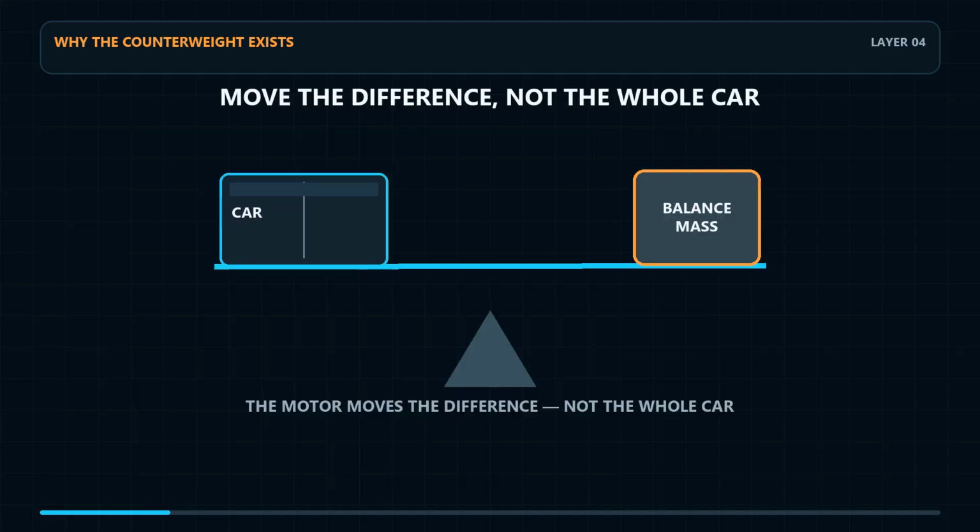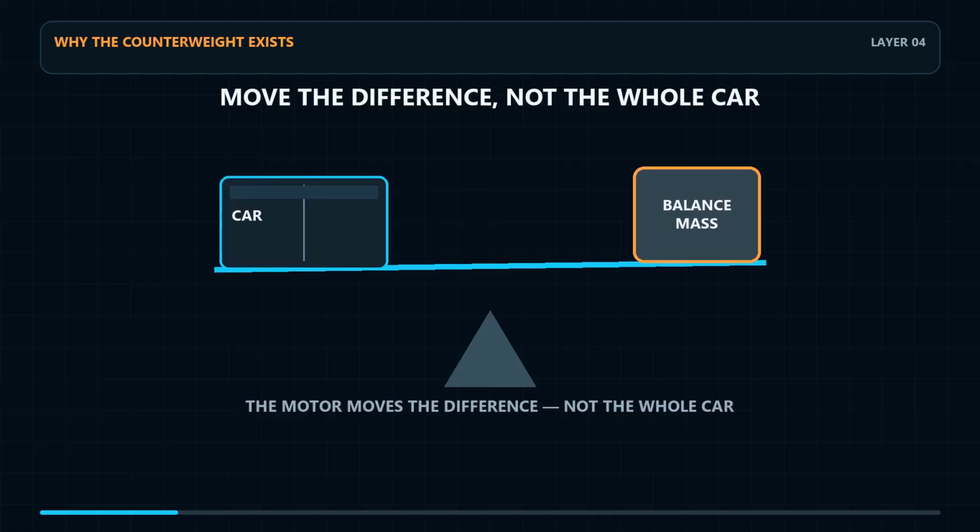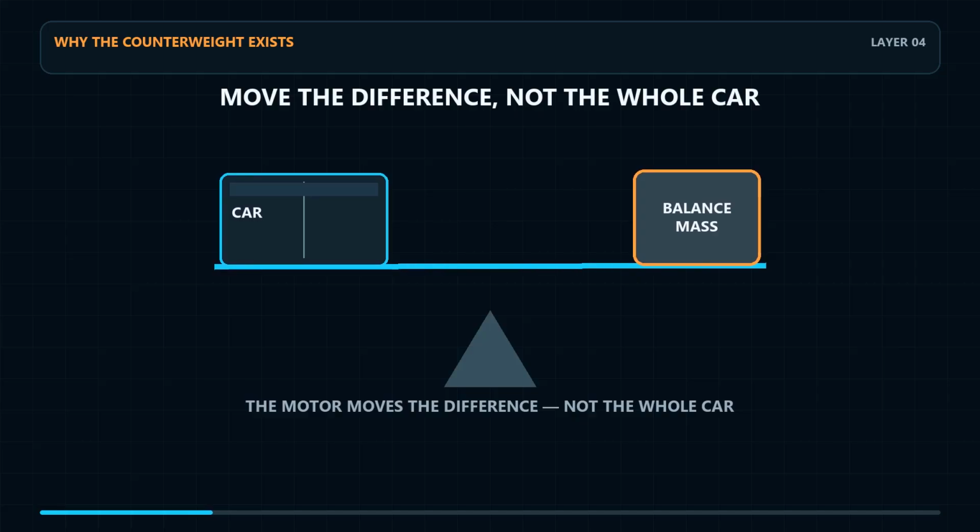The counterweight does not exactly match every passenger. It balances the car and a chosen share of its rated load. That means the machine mostly overcomes the difference between the two sides, plus friction and acceleration, instead of repeatedly lifting the full mass of the car from scratch. Balancing part of the load also reduces the energy the drive must supply over repeated trips.